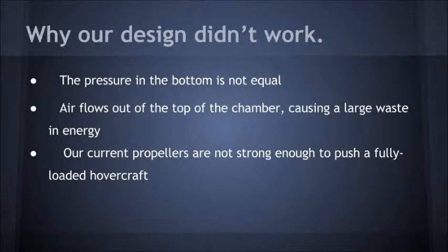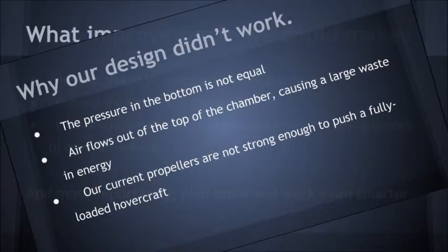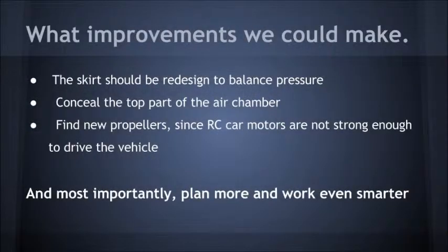However, even when the hovercraft was working correctly, we lacked the needed power of our propellers to move our fully loaded hovercraft. To improve our hovercraft in the future, we would have to fix 3 things: the skirt, the hole above the air chamber, and the propulsion system.